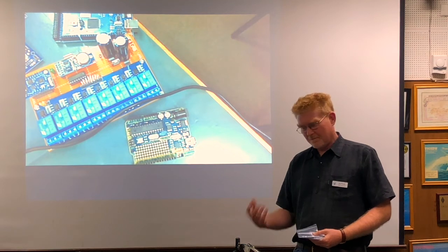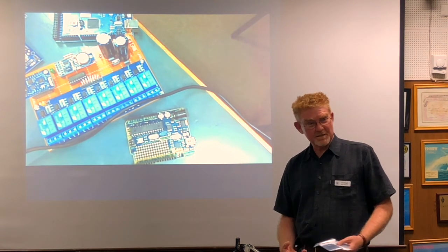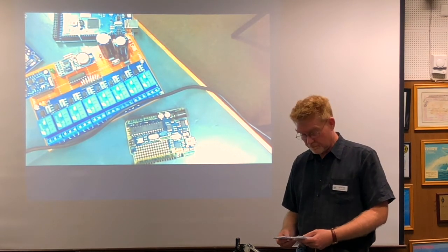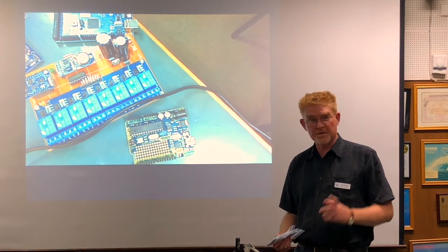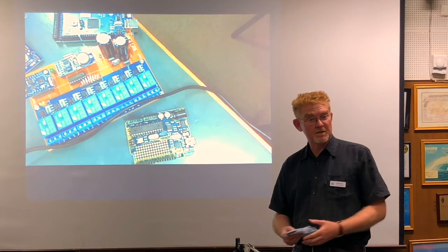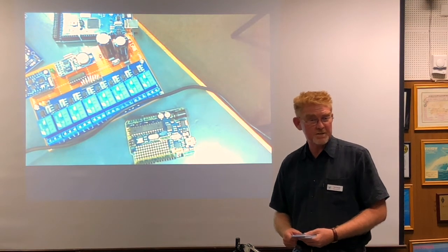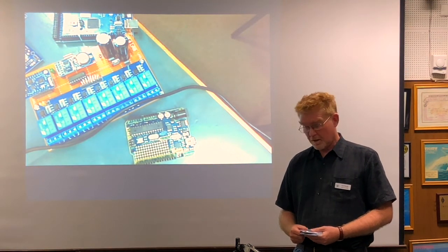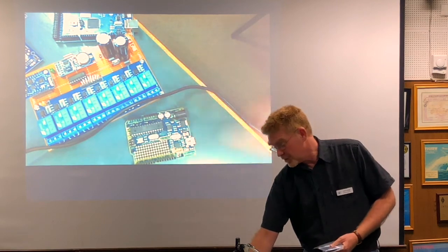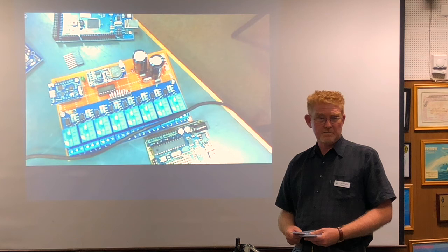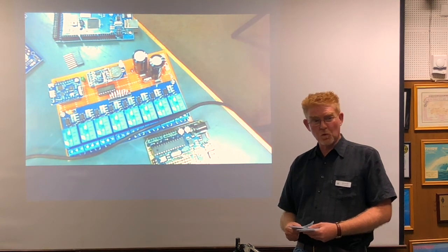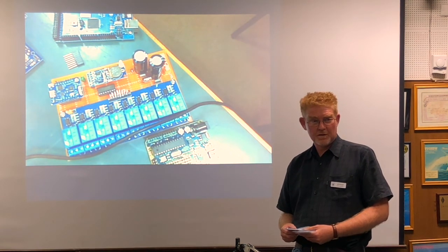I mean, the code there for the Internet of Things, they're certainly smart enough to talk to external web-based services. I've used those to talk to things like ThingsBoard for gauges and so forth, just reporting temperature and light intensity and humidity. You fit that kind of code in one of those ESP modules, and out of the 1 megabyte of memory used for code, I think the biggest I've done is a quarter of that being used.